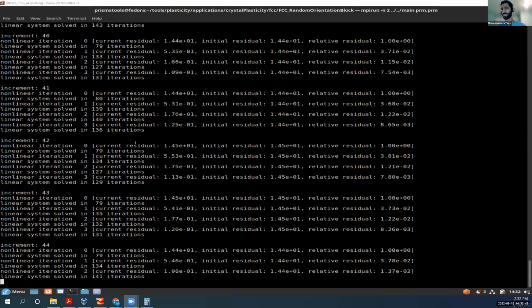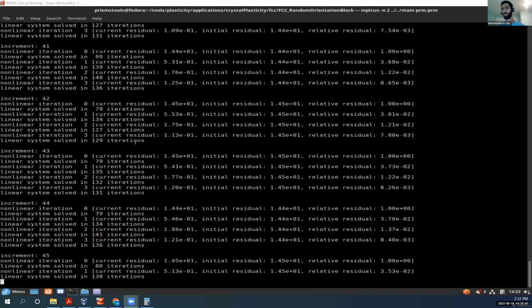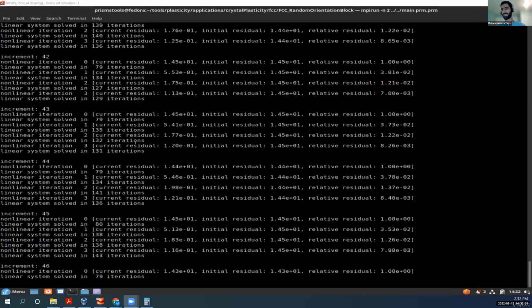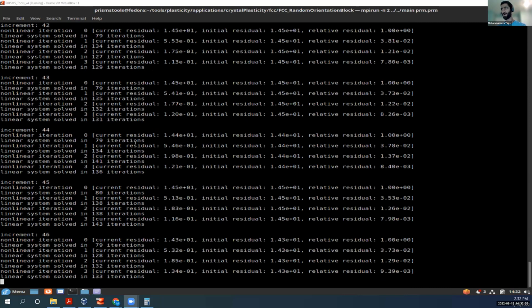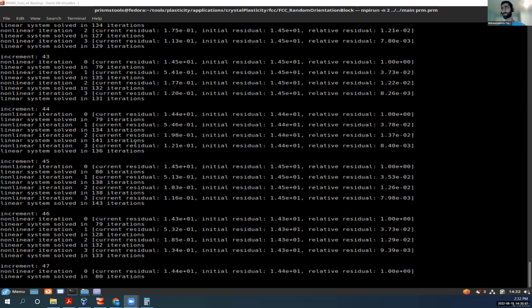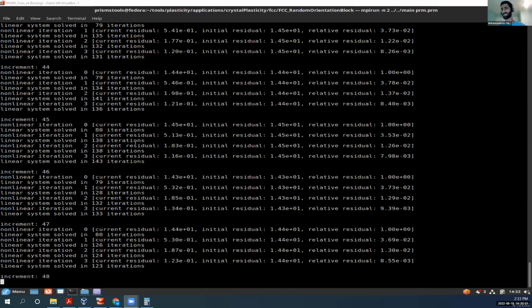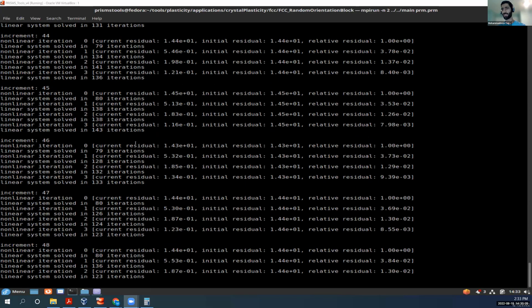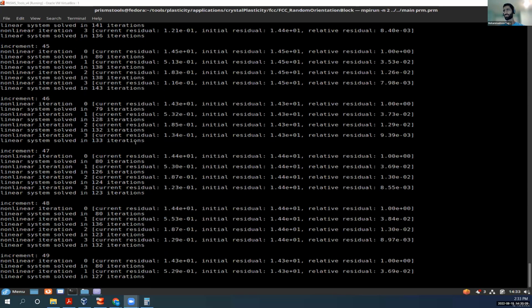If those installed successfully, honestly, nothing should have happened, but some people face installation issues with the newer version of deal.II. So my next suggestion is to try another deal.II version. The current version is 9.4. I successfully installed that with PRISMS-Plasticity on both a cluster and a local machine last week. But you can also try deal.II 9.2, which is a more stable version. Definitely use make debug to see where the error is coming from, and then go from there.